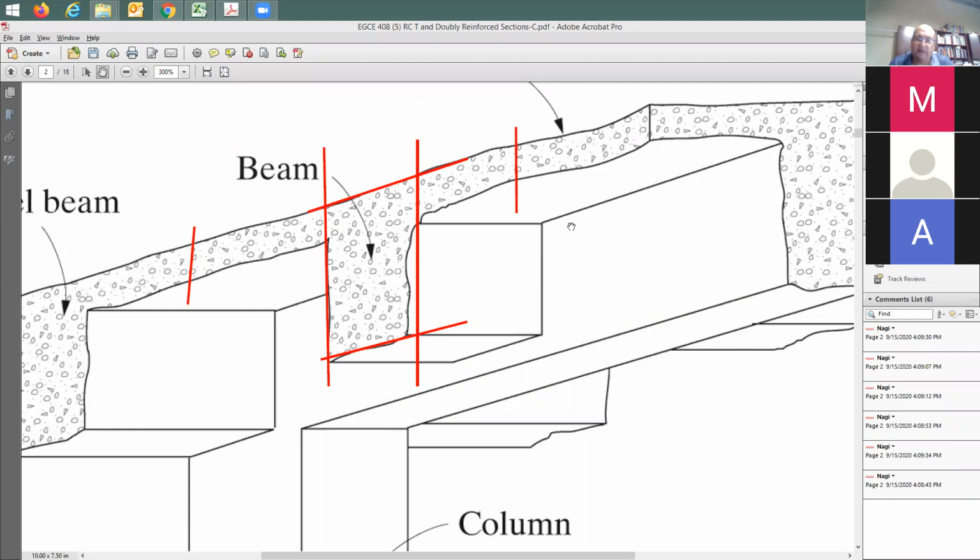Also, I'd like to simplify it if you don't mind. I'm going to say that the T section is going to be stronger. Why? Because you have taken this rectangular section and then, in the area of compression, you start to add more material. So it's going to be stronger in compression, which means most likely the beam is going to be stronger. Does this make sense to everyone?